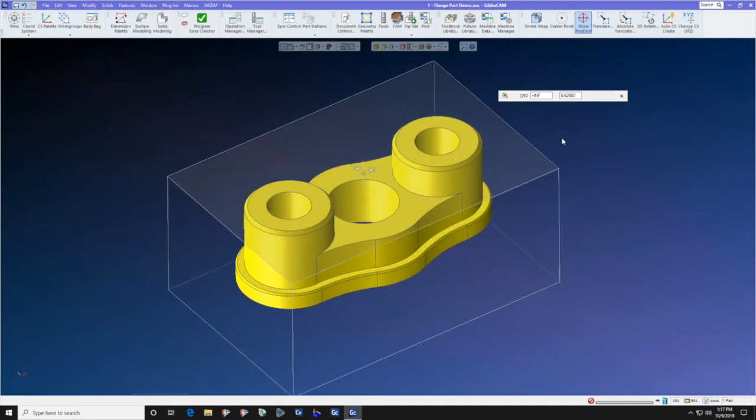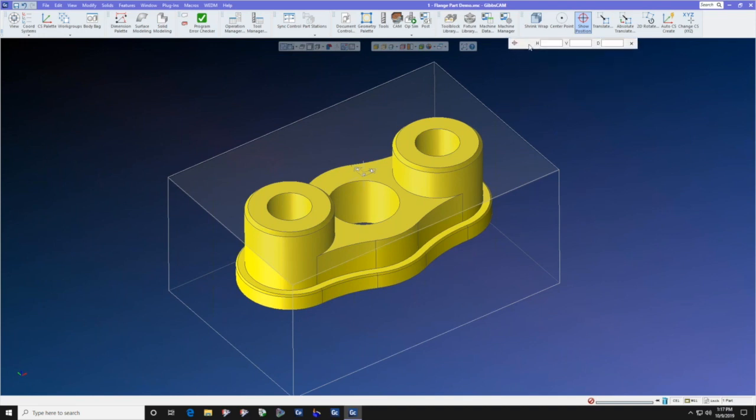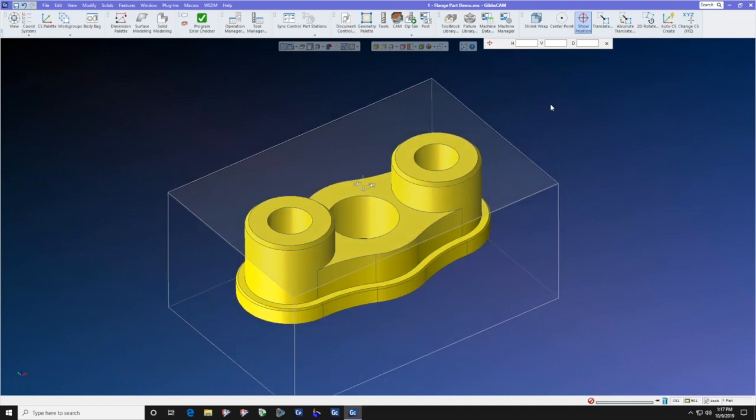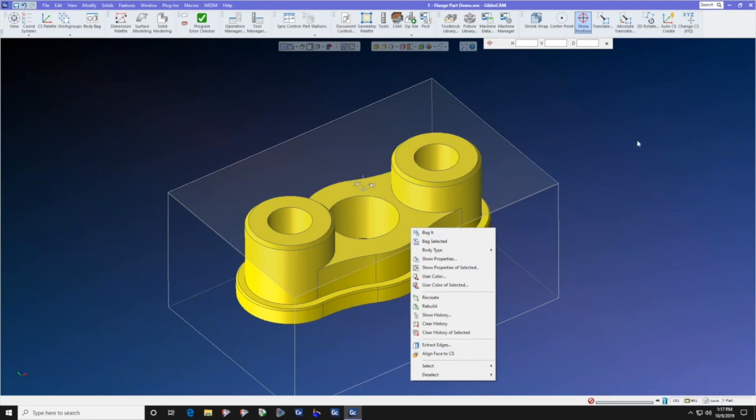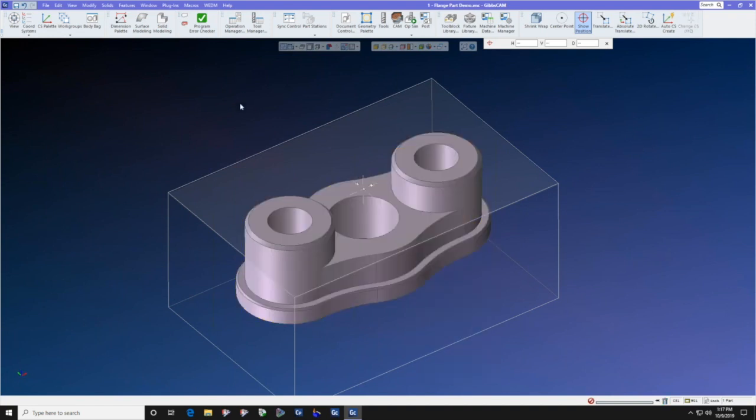part. So now that you know that you can use show position to machine your part, I'm going to leave it right here just in case we need it for reference while we are going to machine the part. Now, so that we have imported the part, we've brought it into place using several different methods, absolute translate and align face to CS. It's now time to set the part up on our fixture.